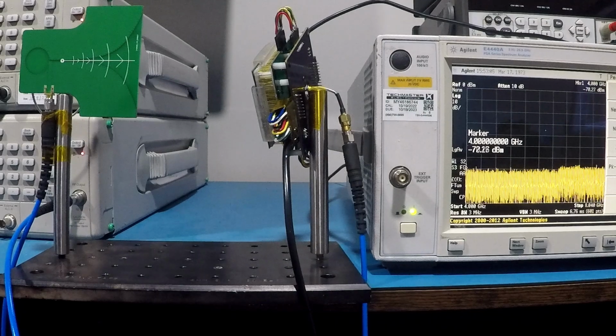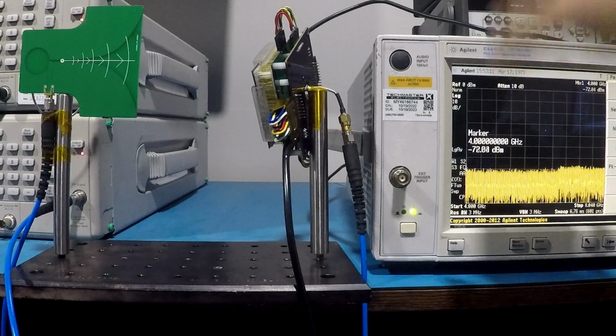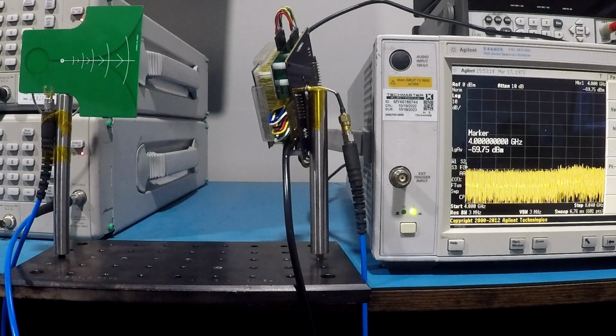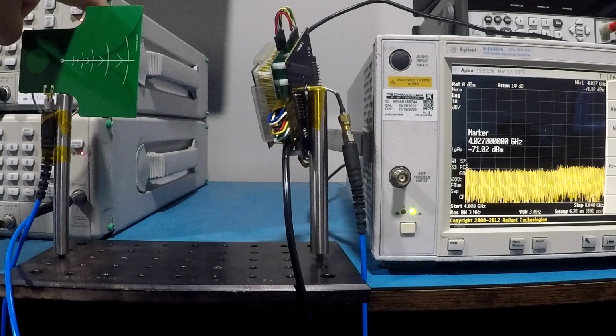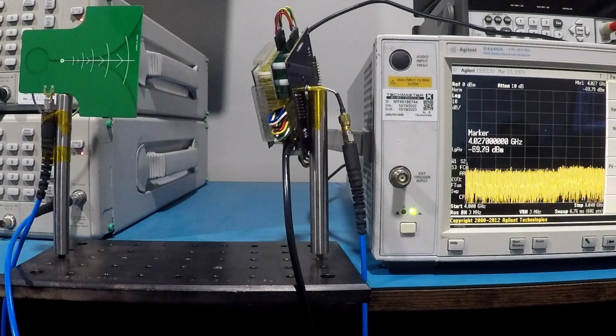So here's the current measurement setup for the next series of tests we're going to do. I have the smart antenna hooked up to the spectrum analyzer. I have a logarithmic Vivaldi antenna hooked up to the bottom signal generator. That's going to be the transmit antenna that's sent to the pixelated smart antenna. And over here we also have a tapered patch antenna that's hooked up to the top signal generator. That's going to be the jamming device that we're going to use to interfere with the transmit signal.